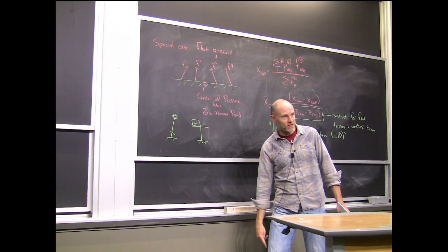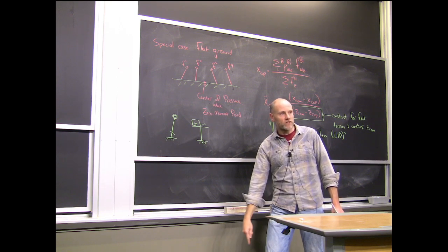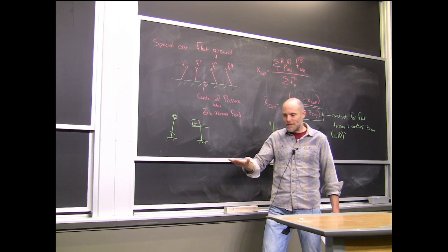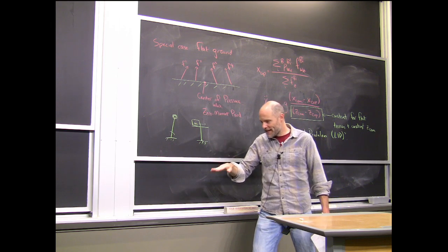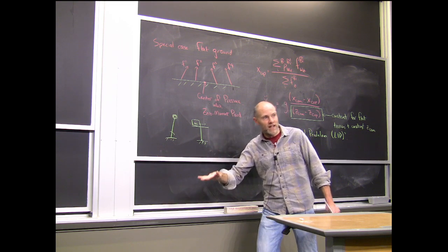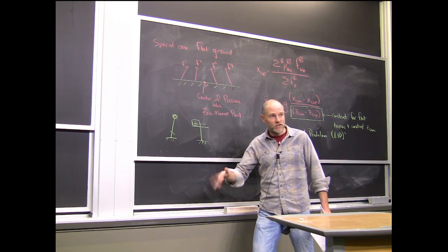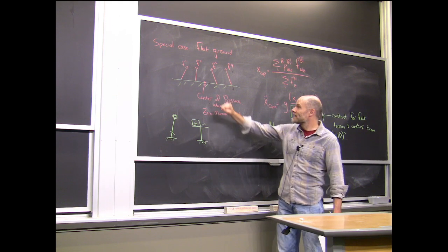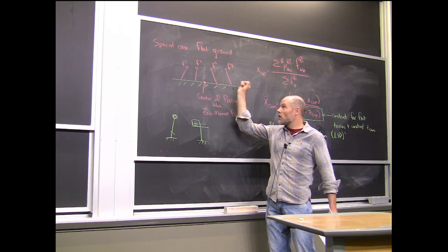If you have force sensors in your feet, you can measure where your center of pressure is, okay, and you can know instantaneously where it is. It also happens to be a fairly easy thing to regulate. I can often change my zero moment point just by applying ankle torque, for instance. And so I can change the center of mass even with fairly simple control, okay? But the big thing is it's exactly what you need to know about all of the forces and nothing more.